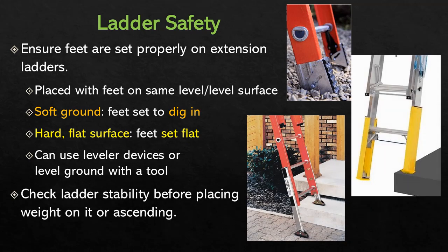You want to check ladder stability before placing weight on it or ascending. You can maybe take a couple steps up on it and see if you notice any shifting, for example. But yeah, before you trust a ladder for you to access several feet upwards, take on the first 1 or 2 rungs and see if it stays stable.